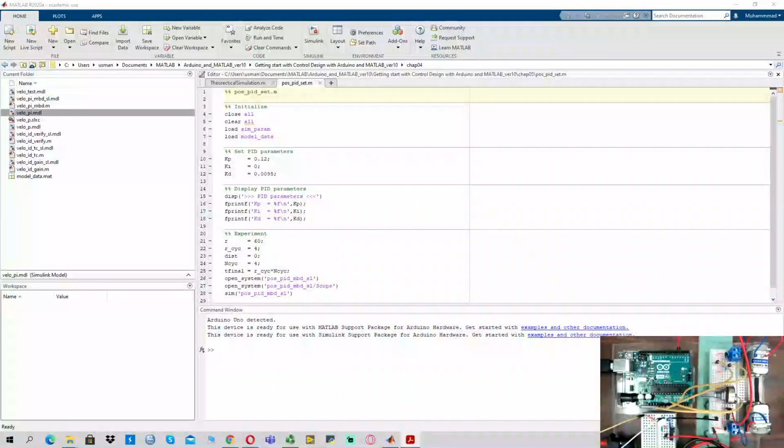So let's start by testing the motor operation using MATLAB. In this case, I will test the general motor operation and try to increase the speed of the motor by using this potentiometer. As you can see in the presentation screen, we have a yellow graph and a blue graph. The yellow graph is the input that we're giving from the potentiometer, and the output we are measuring, the blue graph, is the motor trying to catch up or speed up as we ramp up the potentiometer voltage.